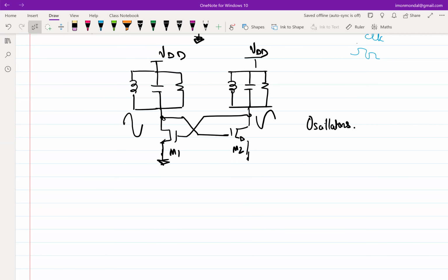So one way to go about changing is having banks of capacitors, maybe multiple parallel capacitors, and tune in and out each of those capacitors as you please. That is a discrete way of going about it, right? Let's say you have banks of 1 picofarad capacitors, 10 of them. In one configuration, you turn on all 10. You get a 10 picofarad cap, and you get an FC. In another configuration, you turn off 9 of them and have only 1. Then you get a 1 picofarad cap, and you get a different FC, right?